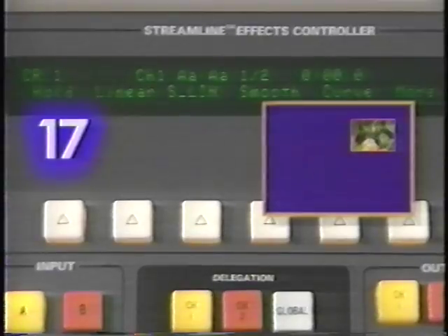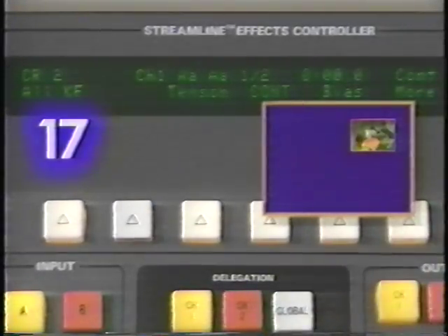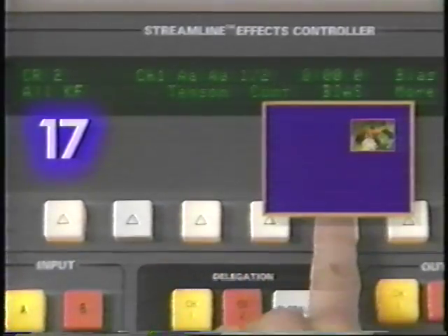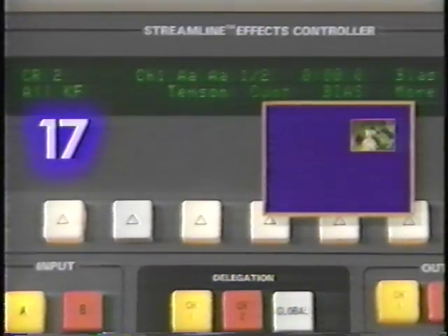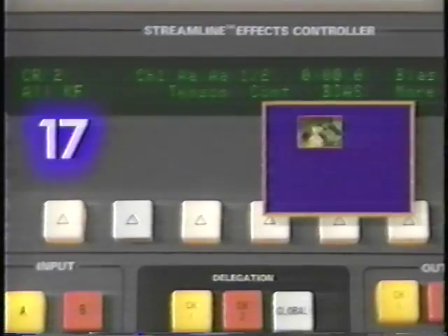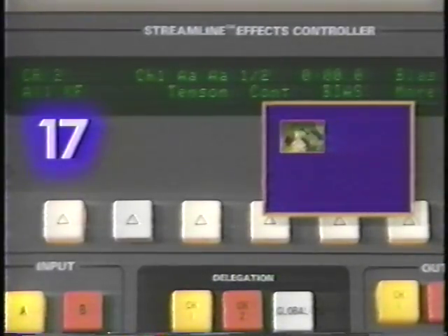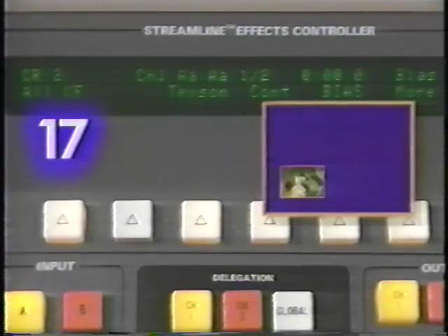If you're editing the location parameter, you can select Curve in addition to the other path shapes. Curve applies only to location. It controls the following 3 parameters: tension, continuity, and bias. These parameters interact with one another. When a value is entered for one, the effect it has will vary slightly according to the values set for the other 2 parameters. Tension is the characteristic of location which determines how sharply the curve bends at a keyframe